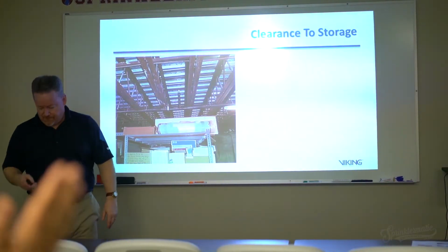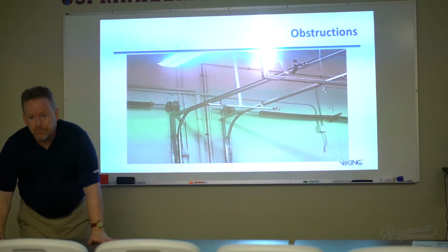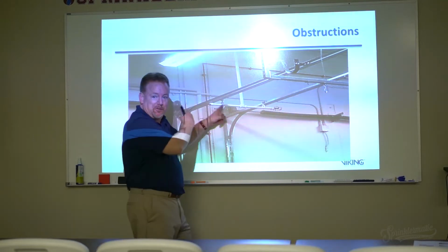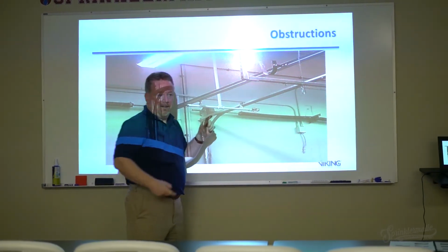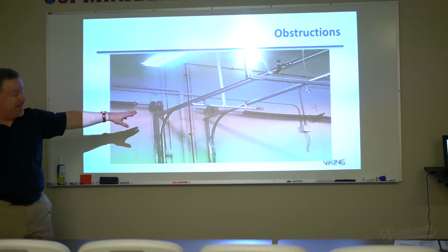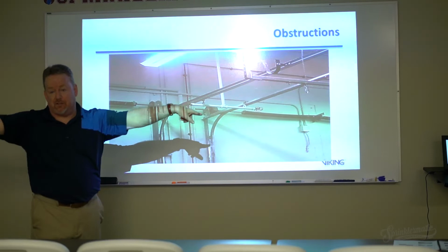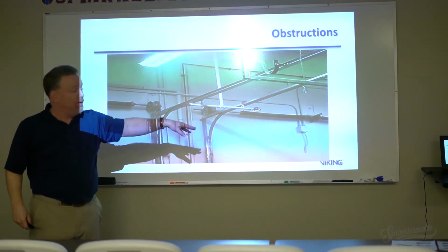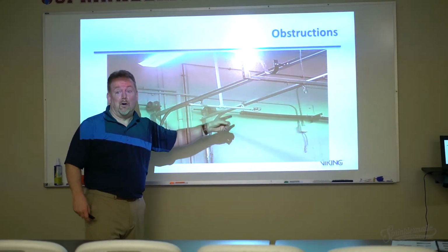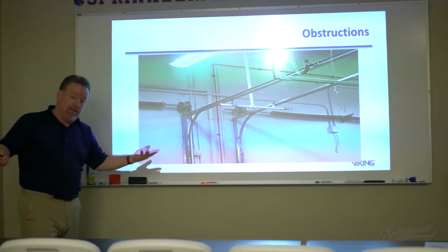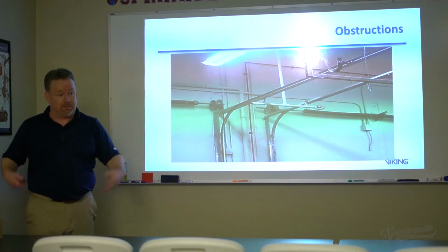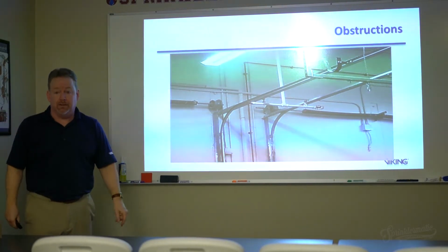At that point, it doesn't matter if you have a closer sprinkler head and the other one. You mean because these are so close? Yeah, these are sidewalls. The best answer to that is these are sidewalls, so they're both spraying in opposite directions. One's not going to spray on the other. The big challenge might be if you get one that's real close to the bottom of one, you might get them both operating at the same time. But again, it's better than having none of them operate because you've got this big 10-foot obstruction.